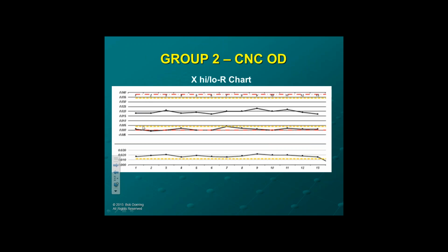But also take a look at here. Here's your 75% of the tolerance control limits, and you have portions of the part that are actually out of spec. That again is not a good thing. So this is a very risky, dangerous process, and depending on where you were to measure that part, you would find not only is it out of control, it's actually out of spec.